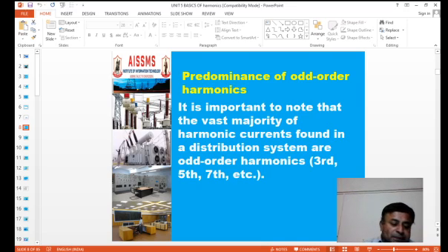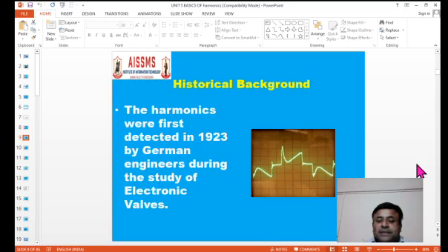So it depends on the type of device where these harmonic components are coming in, and therefore, depending on that type, for example, a personal computer will have third, fifth, seventh. A steel mill or rolling mill may have some different harmonic predominance like 7th, 9th, 11th, etc.